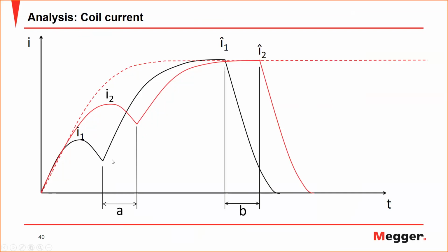If, however, the shift is in the B1 here, let's say that the A shift is almost zero, and you have a B shift here, it means that there is no problem with your coil, but you have a problem with your mechanism. This is very important when you are doing timing tests.